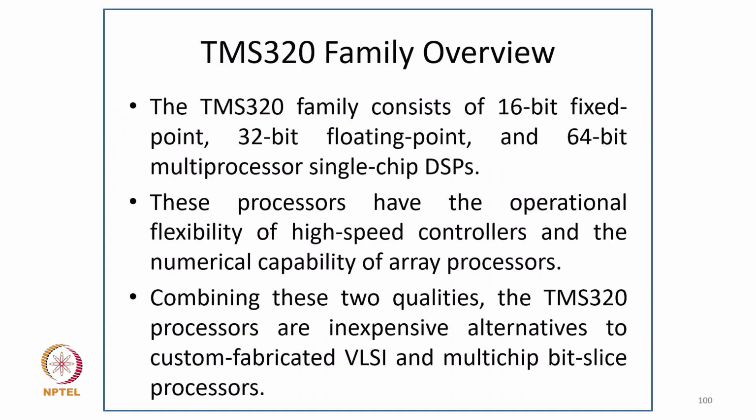So coming to the TMS320 family overview. The TMS320 family consists of 16-bit fixed point, 32-bit floating point, and 64-bit single-chip DSP microprocessors. These processors have the operational flexibility of high-speed controllers and the numerical capability of array processors.